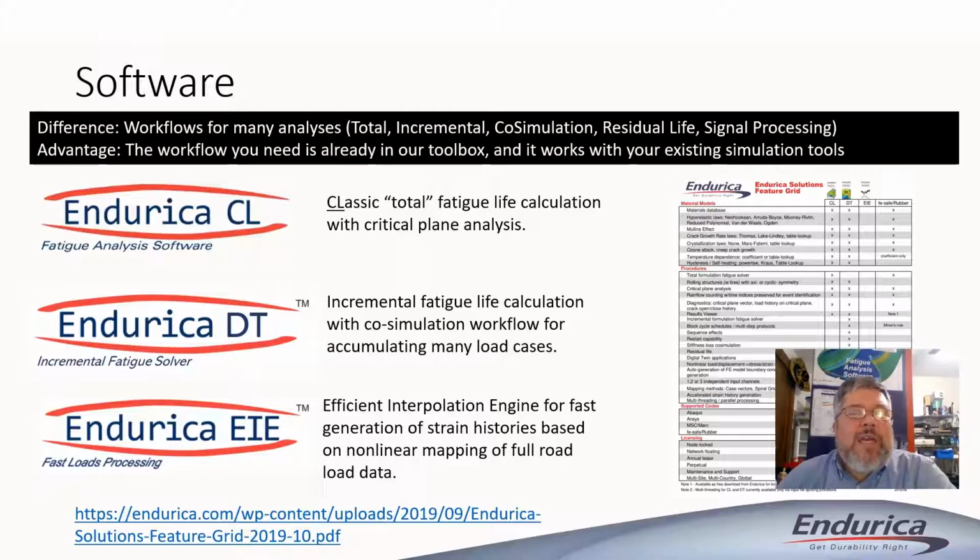Finally, Endurica EIE is our efficient interpolation engine. If you have a load signal that is maybe so lengthy that you can't simulate it with your FEA, if you've got 1 million time steps, 3 channels that maybe you recorded at a test track, maybe you can't run that in a finite element simulation, but you can use EIE to convert the load history into strain history that you can use for fatigue analysis.